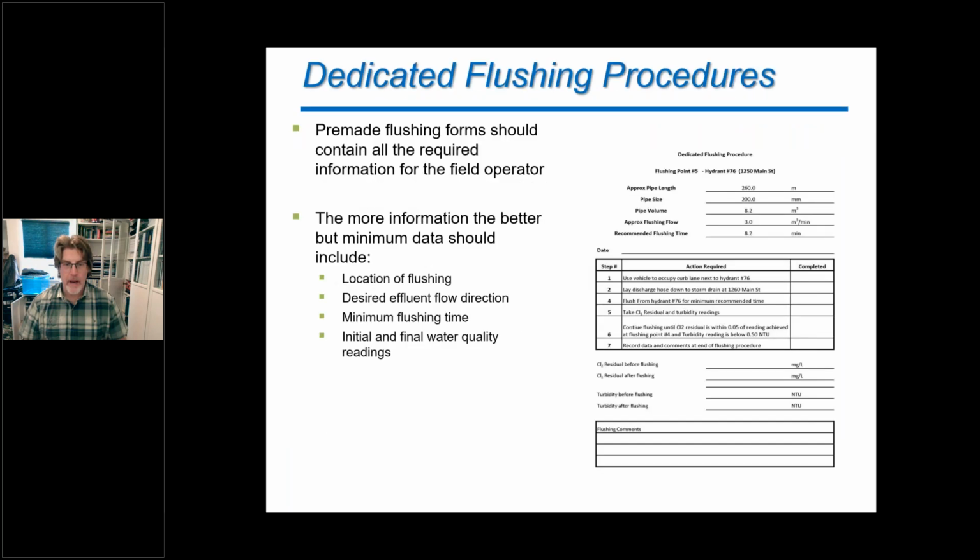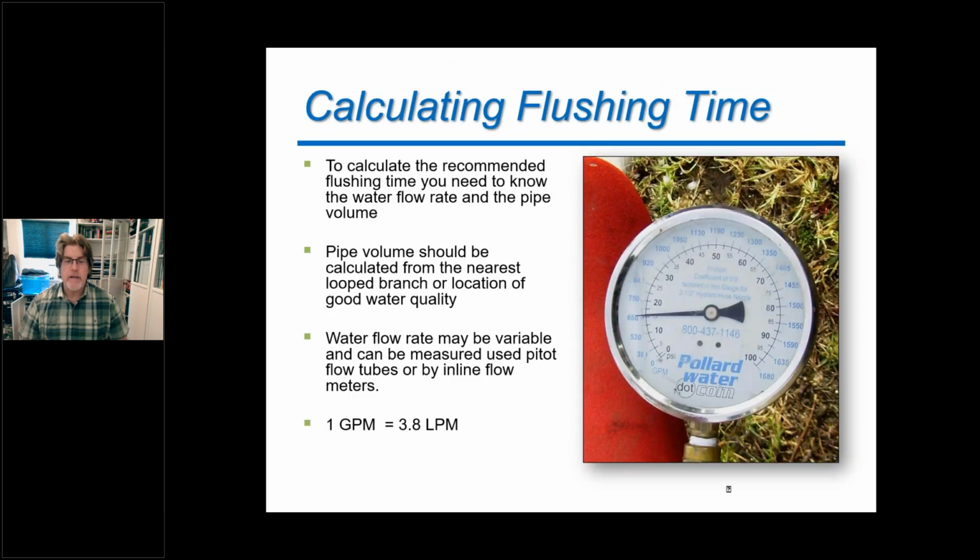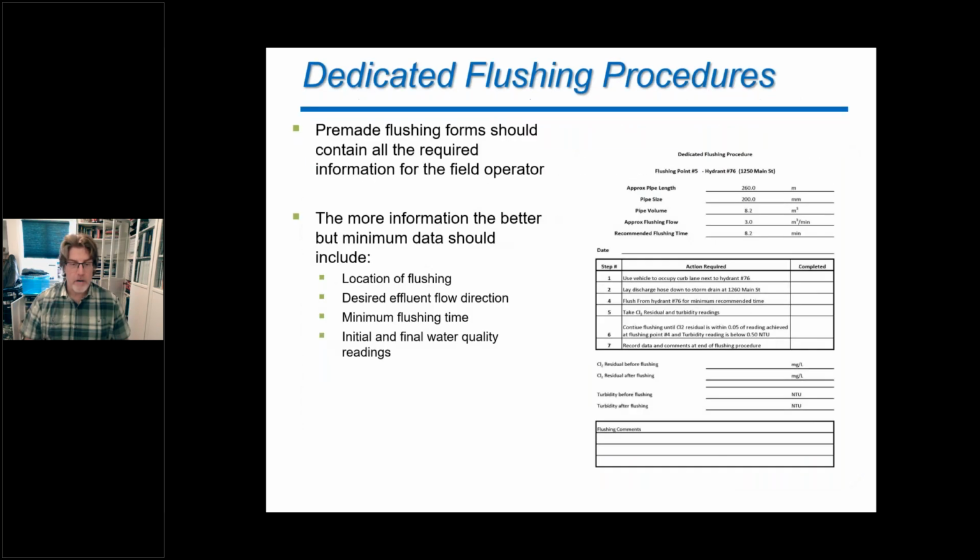And I'm just going to go back a bunch of slides, but this is this gauge here, right? Might be a little bit hard to see in here, but the outside ring, that is measuring flow in gallons per minute leaving that discharge. So this one here at this hydrant that we're using, it's reading 650 gallons per minute coming out of that hydrant. So if we look at the chart,